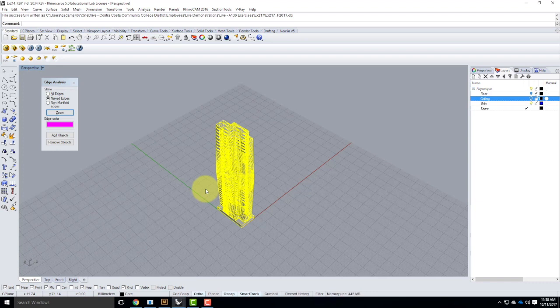So you'll come over with your object file, and then you'll write something that's called G-code. That is the computer instructions that tell the 3D printer where to go and how to extrude the material. Once you have the G-code file, which is a separate file you'll save, so you'll convert the object file into the G-code file. Then you'll load the G-code file into the 3D printer and essentially say print. And it'll sit over there for hours and do its little printing thing.